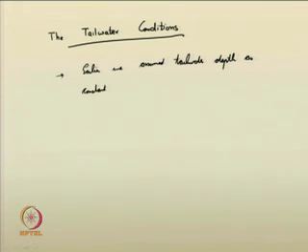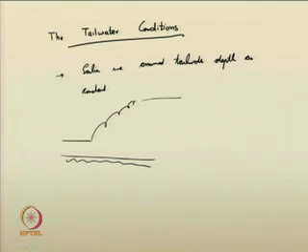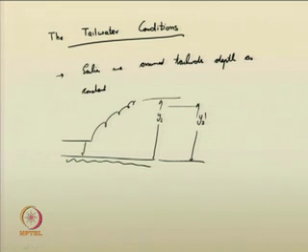Based on that, we suggested, see, this is tailwater depth y 2 dash. So, you do not know whether the jump, sequent depths of jump y 2, y 1. Based on that, we suggested the jump can move upstream or it can be pushed downstream and all. So, there in all cases tailwater depths were considered as constant.